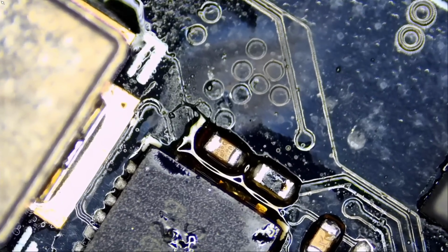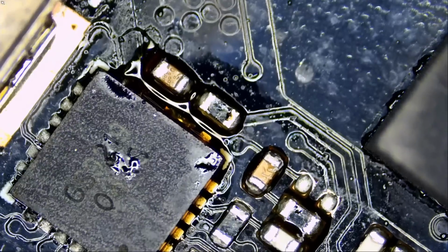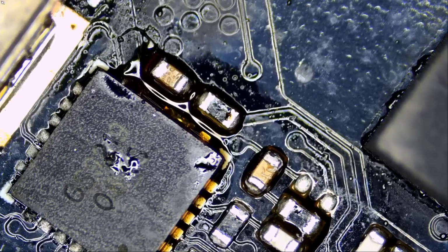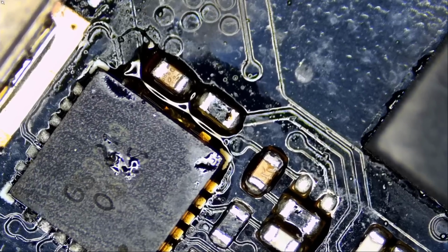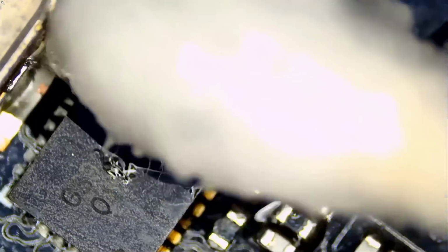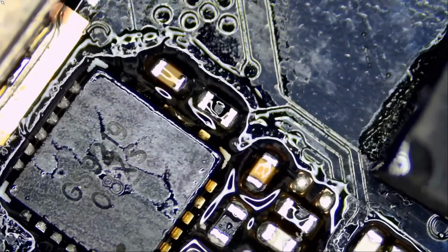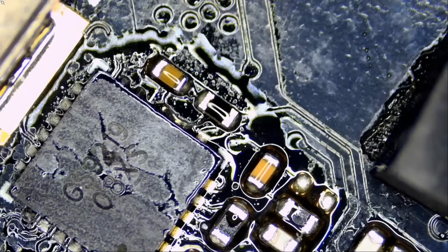That's why components are placed next to the chip, so we can transfer excess solder onto them. Now it's okay if those pins bridge because they're all connecting to the same pad.